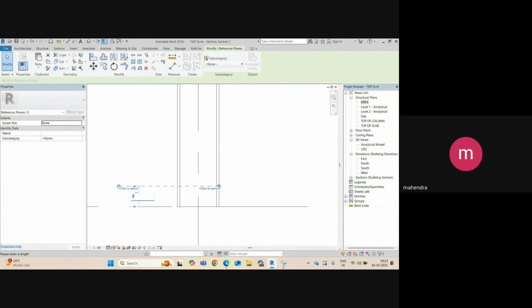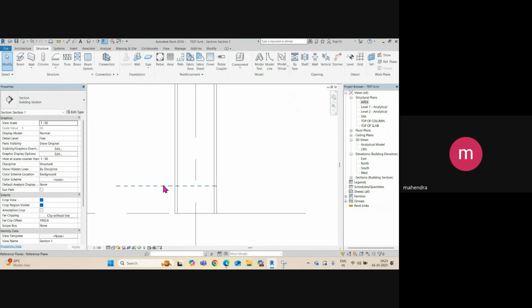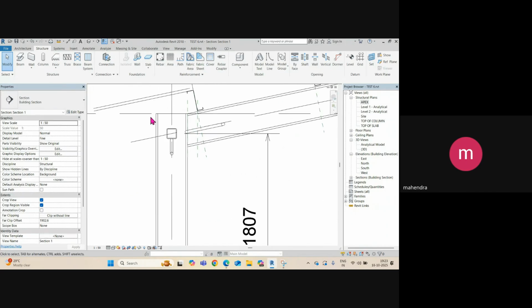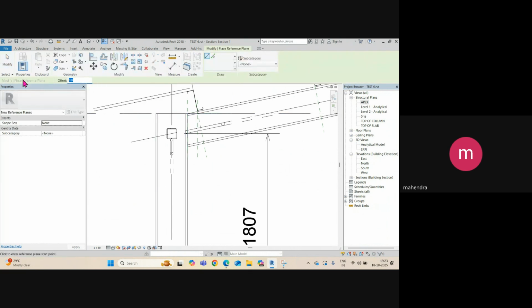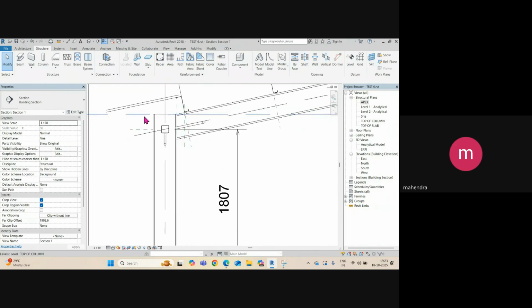So suppose I will give here 200. Right. So first side guard will be here. Then above I will add here also 200. So type RP and 200, because exactly on the top and exactly on the bottom we are not able to add, because we need to give the connection also. So you need to give some tolerance here.